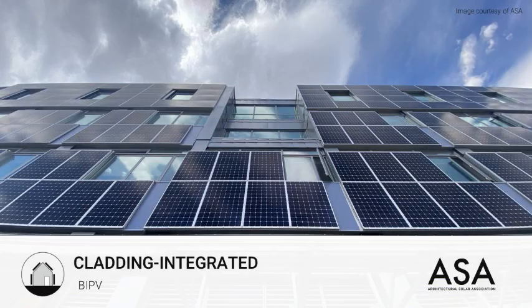Cladding integrated PV is one degree closer to envelope integration by being components of a roof or wall assembly. Typically, this is in the form of an outer weather barrier. Roof integrated cladding offers the best energy production opportunities, while wall systems can provide increased energy generation when expanding beyond the rooftop is required.